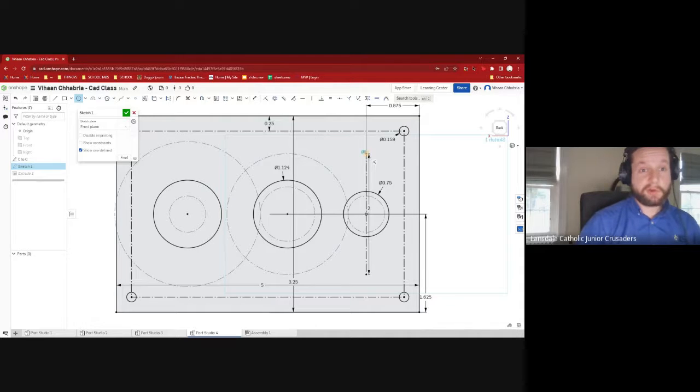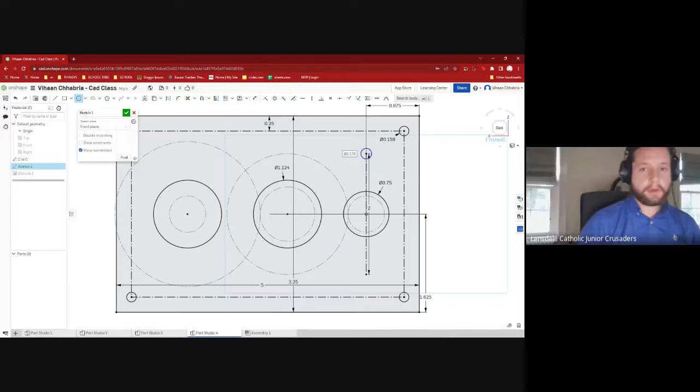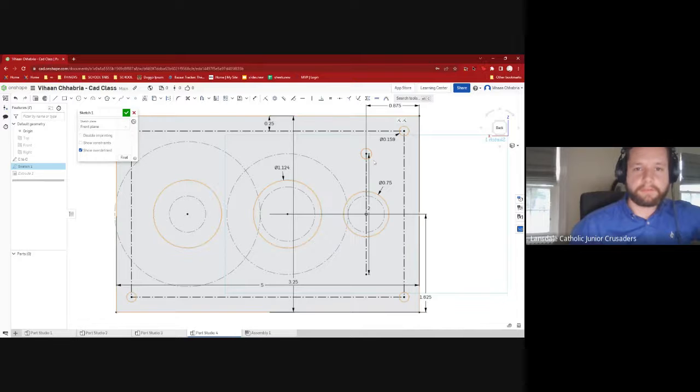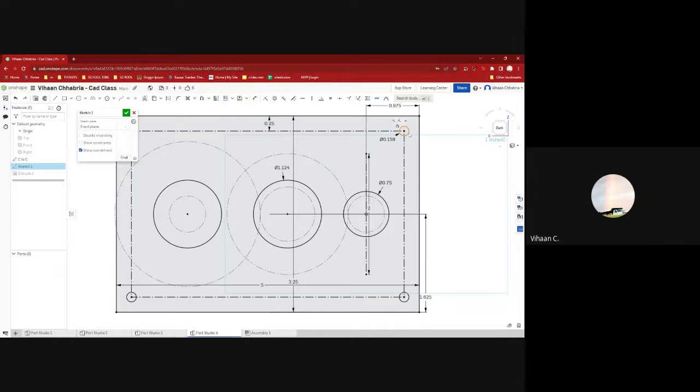There's also an actual hole feature that will help you make holes of the right size. Do you want to try to use that feature? Sure, I guess. Okay, cool. Delete all of your circles then. All of them? Yes, but keep the other points and lines that you're using to reference it. Oh, sorry, not the circles for the bearings, just the bolt circles. So delete all 5 of them. These two. Yep.